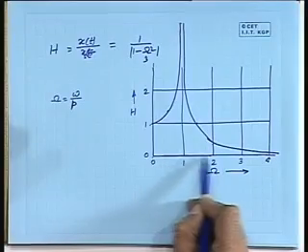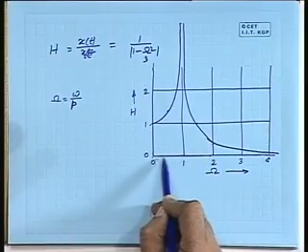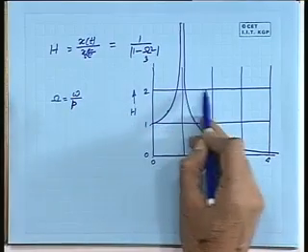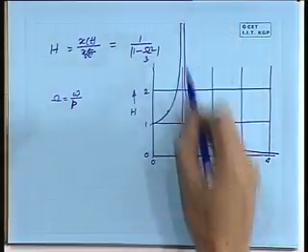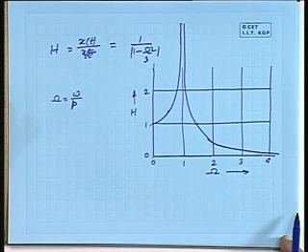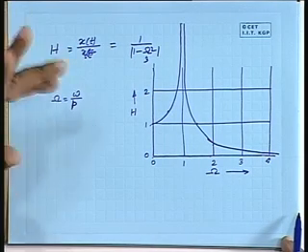In that case you will find that suddenly the thing goes up and then comes down. What is actually happening is he is trying to move the RPM from here to here. In the process, this zone is getting crossed, and therefore the displacement is jumping to this high value and then coming back, and that is what that rattling sound is at times.